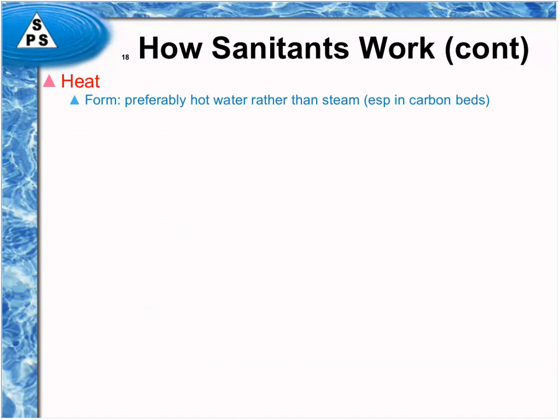It's preferable to use hot water than to use steam. And this is my strong opinion, especially if you're trying to sanitize a carbon bed. If you use live steam to sanitize a carbon bed, you can pretty much be guaranteed that it won't be effective. The steam tends to channel through the bed and doesn't heat the whole bed up, unlike hot water that will flow through the whole bed and heat the whole bed up. You don't have to have steam types of temperatures in order to kill the organisms that grow in a water system, because they're very susceptible to heat.